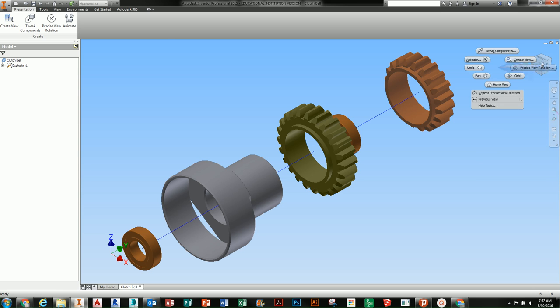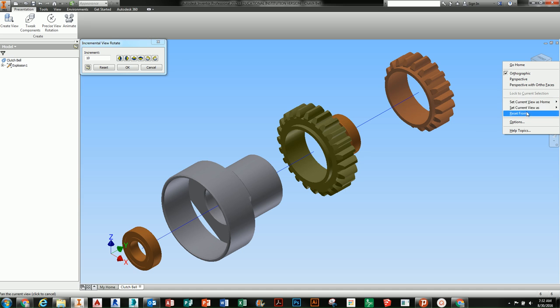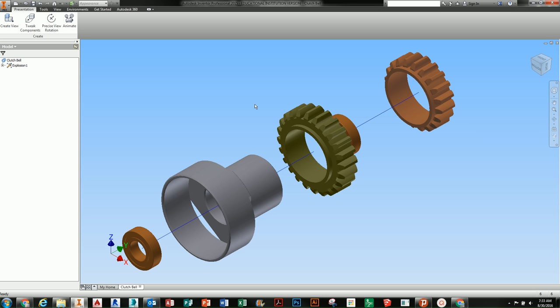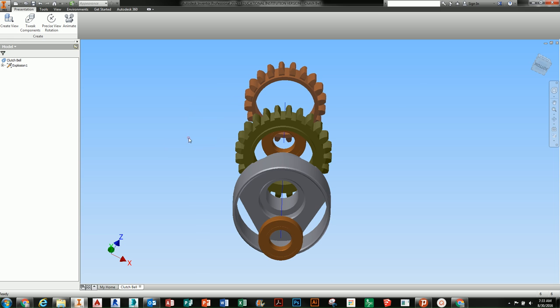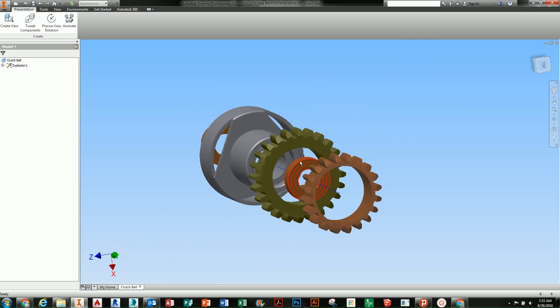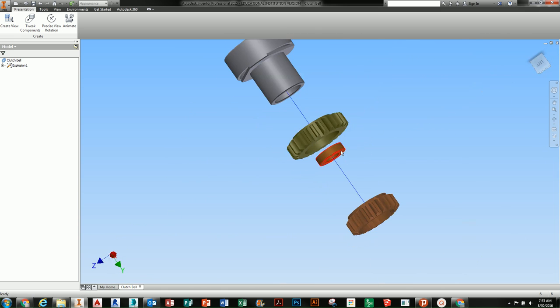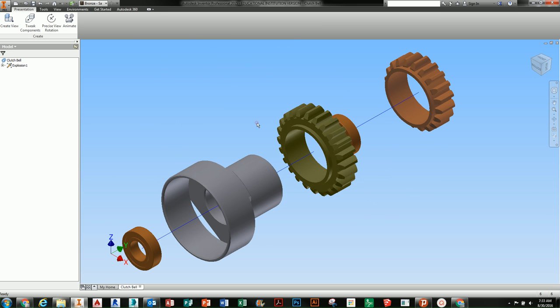So in some cases you might be able to right click, go back to a current view, or change the initial location. And then we can also come back here, we can right click, and then we can go Restore Camera, and see it'll take you back to your home view. So if I move all around and I want to edit some components, move some things around, I can always right click and go Restore Camera, and it takes me back to my initial camera animation.